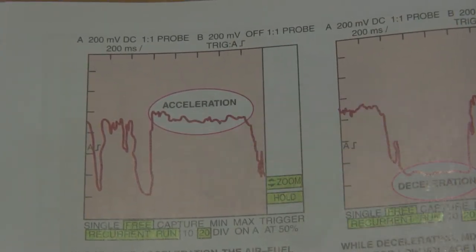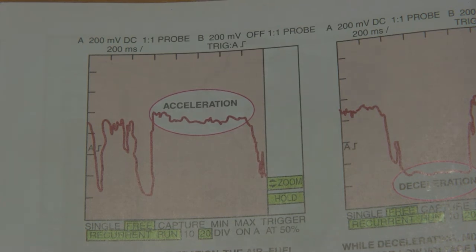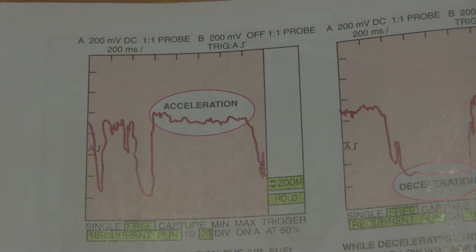If we think back to what I said, oxygen sensors that are narrowband do not have the ability to see outside of the stoichiometric spectrum. And so the stoichiometric spectrum is your 14.7 to 1 air-fuel ratio, a little bit above and a little bit below. So if 14.7 is ideal, 15 to 1 would be on the lean side, 14 to 1 would be on the rich side. Your narrowband can only see tunnel vision. It cannot see much further out than stoichiometric.